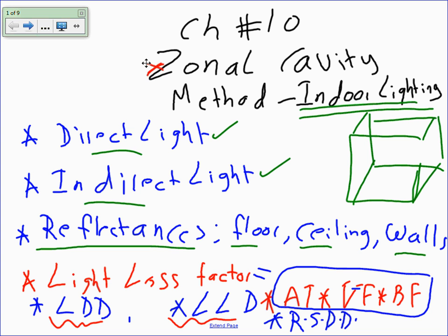How do they affect and how much they affect? You guys look at your book. They have for example, room surface depreciation factor. If it's very dirty, they have a list here. If it's very clean, they give it 0 to 12% factor. If it's very dirty, you can get it to 60%. Be very careful when you use it though. You might have to use the opposite. If it's extremely dirty, it's 0 basically. If it's very clean, it's 100%. So it doesn't affect your numbers.